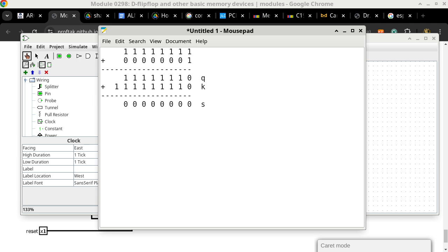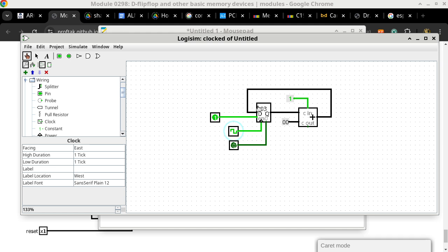The second way to answer the question is to go back to Logisim and turn this to FF. You can click using the poking tool. You can poke a register and then type in the hexadecimal digits into the register to force it to a particular content. So when I have the next rising edge, it would do the same thing that I demonstrated a little bit earlier. This is a falling edge, nothing happens. Now it's the rising edge, and you can see how it goes from FF to 00.